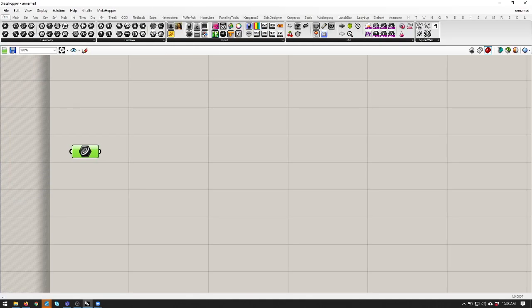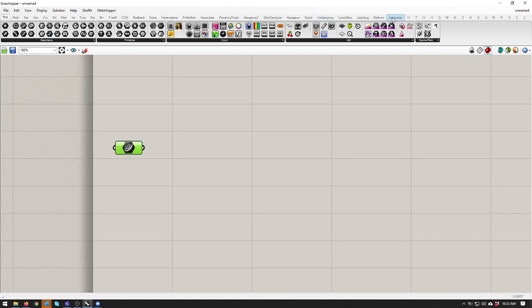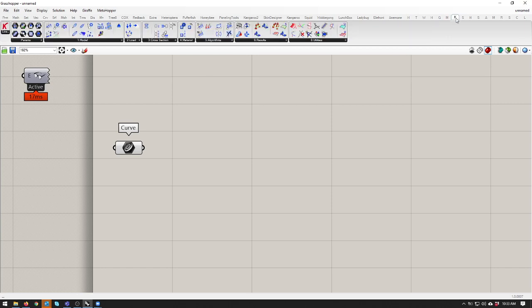If we look at Karamba, Karamba is designed in a way where you have to basically design a model and assign properties to it, and then you put that model into an engine to calculate it, and then that engine spits out a solution model, and there's a bunch of tools that allow you to then analyze that solution model. So first, we've got to build our model.